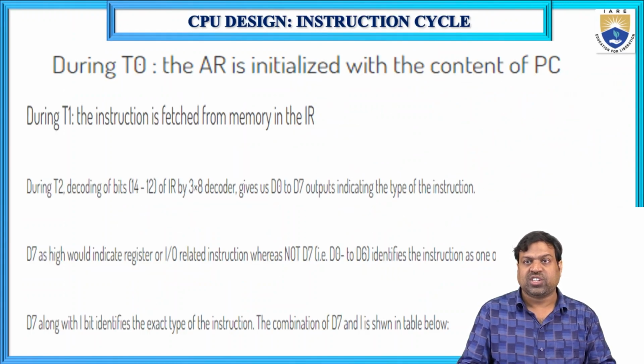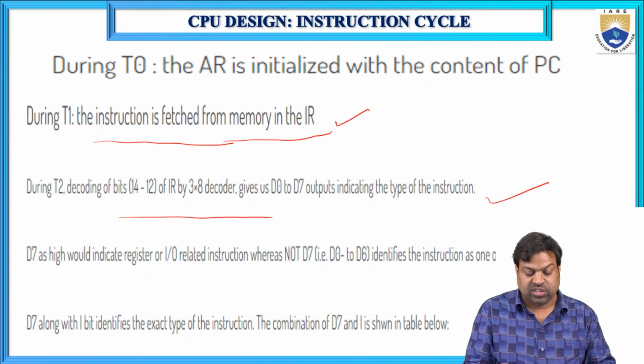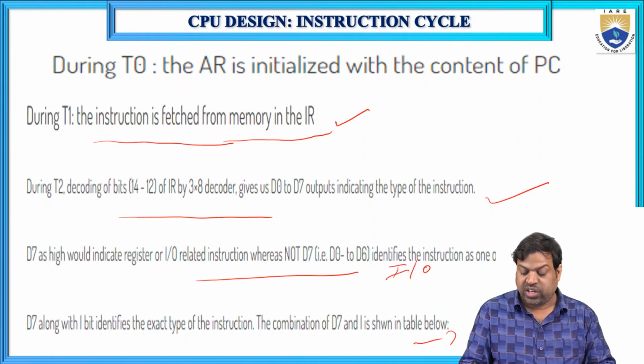And the address register is initiated with the PC. Okay, first T1 cycle, what will happen? It is fetching the instruction. Okay, in T2 it is going for the decoding. After fetching and decoding, it is going for the execution.